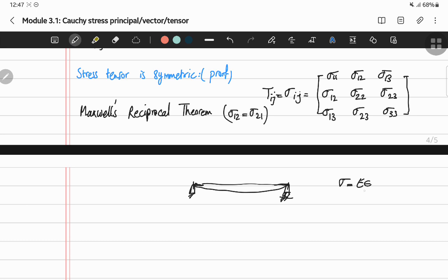So you don't apply the load instantly. So then you apply the load, for example, P1 and P2. So you first apply P1, and then you measure these deformations at 2 points, and then you add this P2.